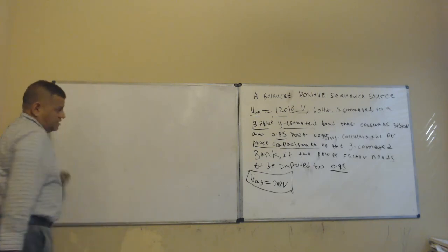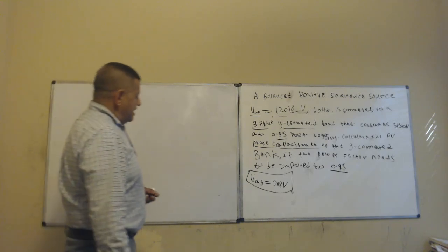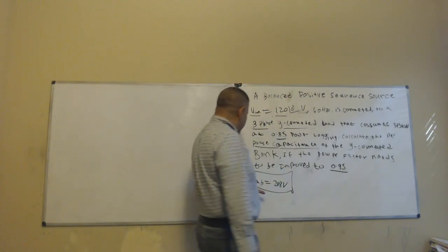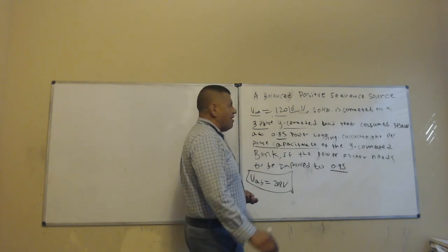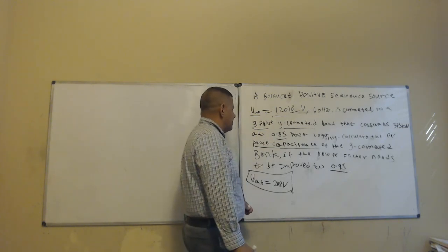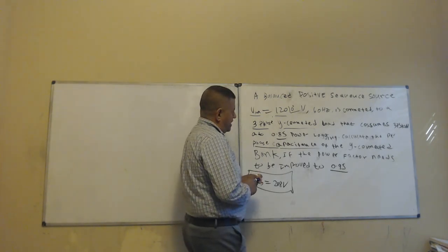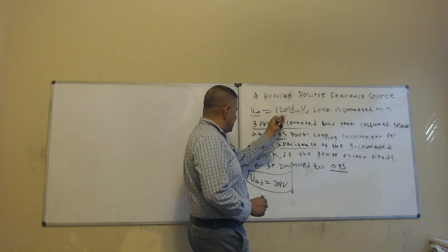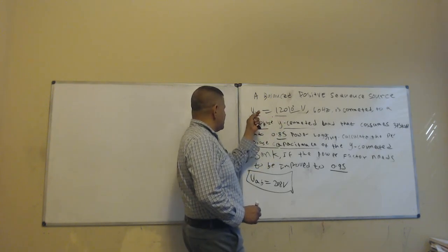So now let's do it. They're giving us some numbers. We found this one using that one. And this is about problem solving, like I previously said. You need to think about it: what is given? Well, it was given, but I'm not going to use this 120 volts directly because it's VAN.